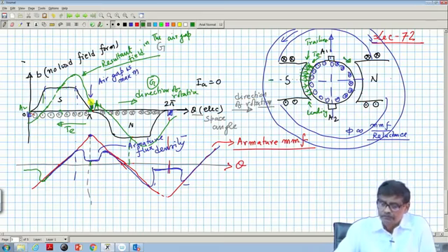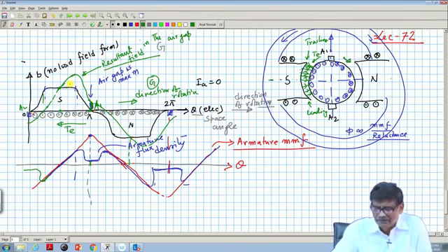and therefore, there may be a voltage loss, induced voltage loss, that is phi no load and phi loaded condition, flux per pole will be slightly lesser. It can be taken into account by some factor, maybe 5% flux loss takes place for large value of armature current.